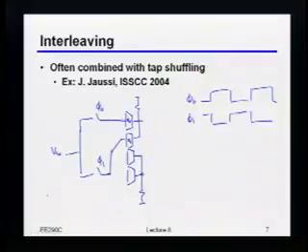So here, my A0 would come straight from that phi 1 sample, because that's my cursor. And my post cursor would be coming from the other interleaved phase, because if I was at this time, then one before me was phi 0. Okay? Does this make sense to people?